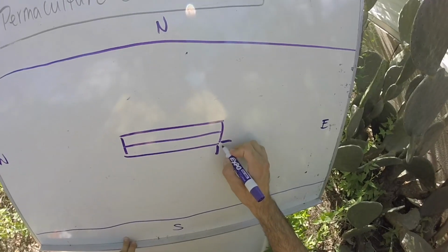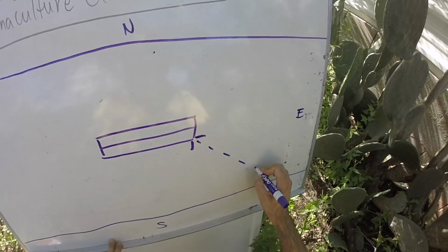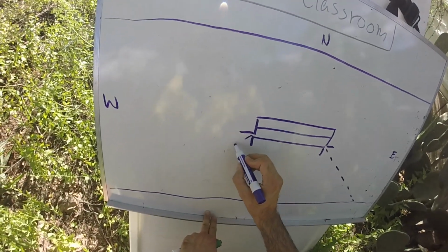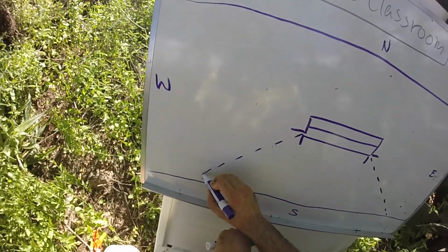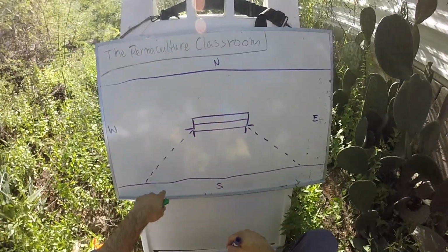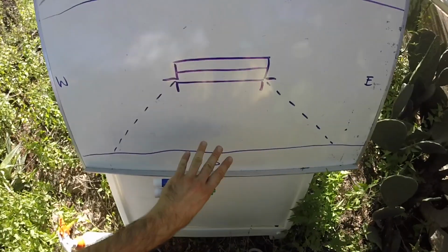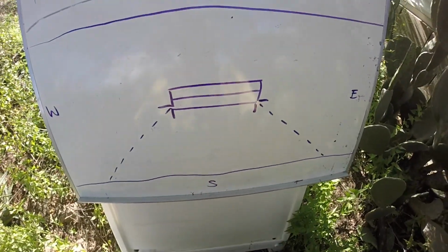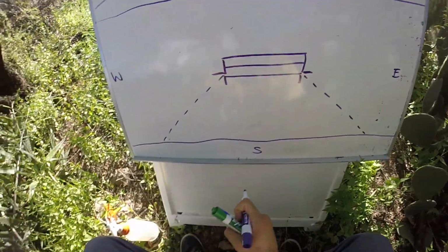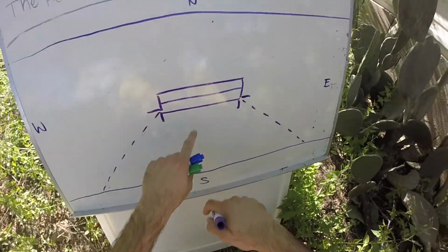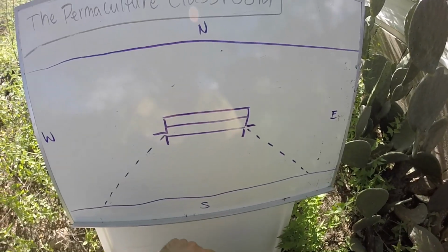Okay, so now we're going to design a site, a fresh site. I'm going to do my 90 degrees and 45s to the edge of the property line. That's step number one. The second thing we're going to do is draw in our master solar arc. And we want to maintain our solar access zone. We don't want to put any huge trees in this solar access zone.